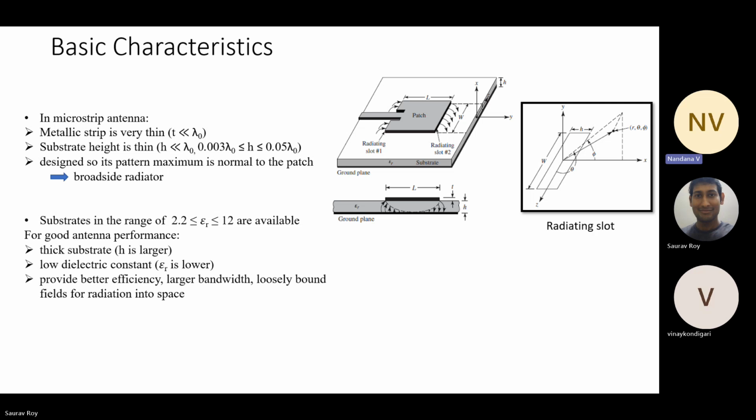It says maximum normal to the patch, or broadside. Which direction? X direction, right? Yeah, exactly. So this X direction is the normal to the patch. So we want a broadside radiation in the X direction.